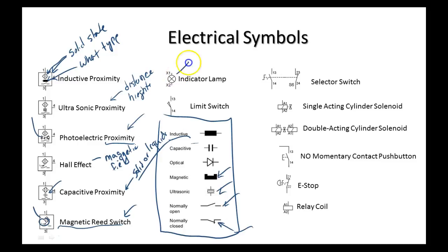And this is a what? That's an indicator lamp. Everybody okay? This is a limit switch. This is a selector switch. Don't know what a selector switch is? That's that reset switch over there. So you got 3 positions on that. You hit it to reset. Then you got manual or you got what? That is what a selector switch is. So a selector switch has multiple positions.